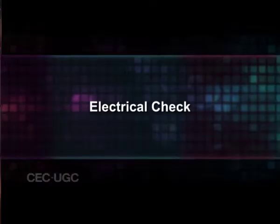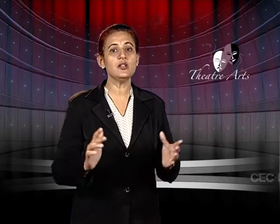To avoid an electric shock, always remember to unplug a luminaire before attempting to maintain it. Electrical check. Check cable tails visually for splits or breaks. Check the plugs. The colored wires should go to the correct pins and all the terminal screws should be tight. The cable's outer insulation should take the strain in the cable sheath grip, so that the electrical connections inside the plug are not put under stress.